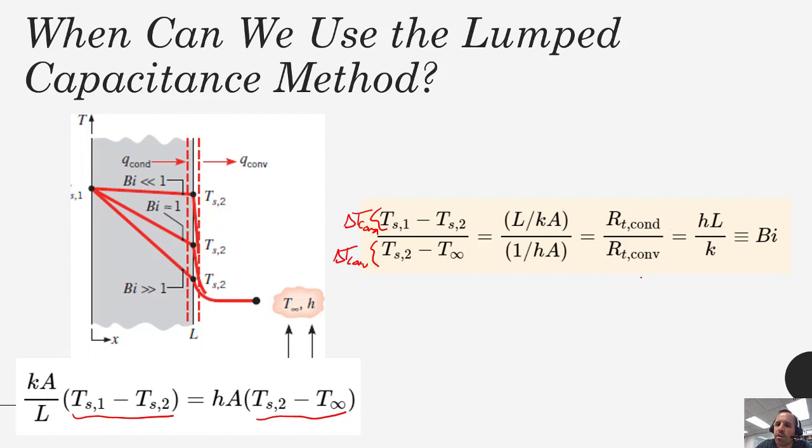So when the Biot number is very, very small, that implies that k might be really large, or h might be really small, or L might be really small. That would imply that there's going to be a pretty shallow delta T through our solid, and that is shown here. This line is a system that has a really small Biot number, whereas this bottom line is one that has a comparatively much larger Biot number. The system with the larger Biot number also corresponds to the largest temperature difference in our solid. So if conduction happens really, really fast, as it does with this top line, then we can make a better approximation that the temperature is uniform for that particular solid. This Biot number is going to be our test for how we figure out if we can apply the lumped capacitance approximation.